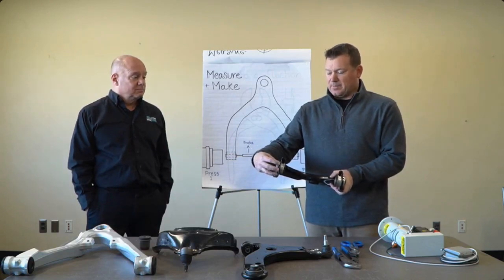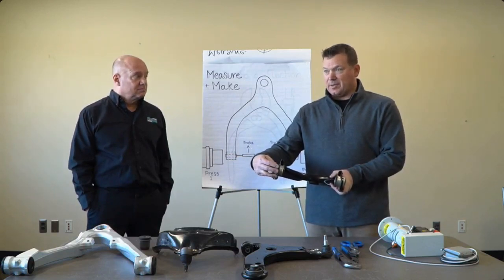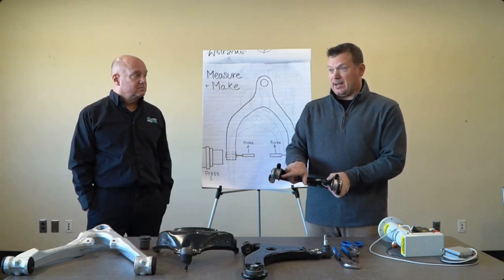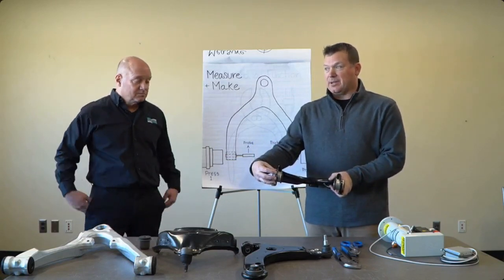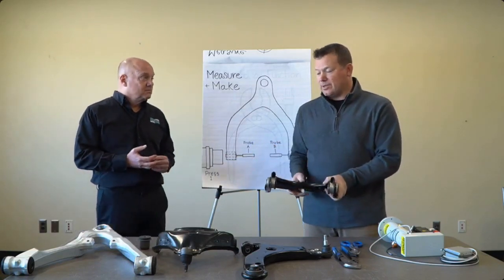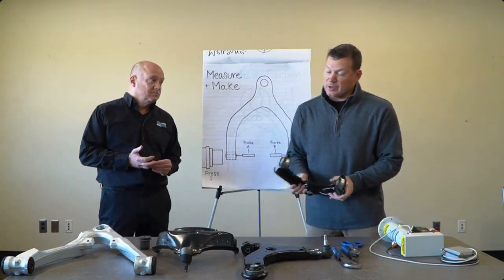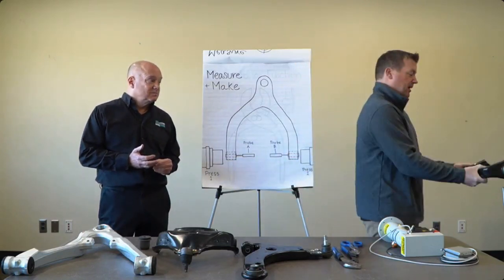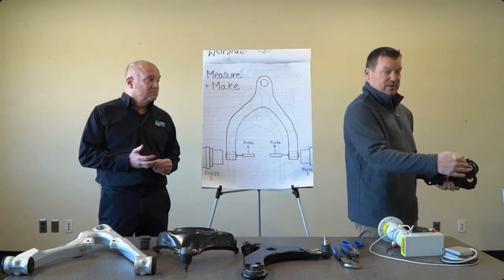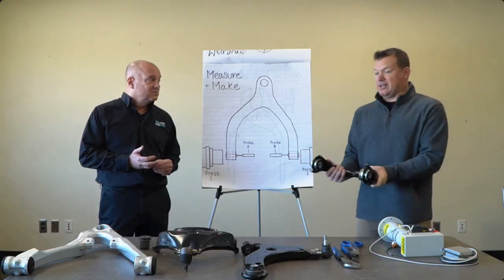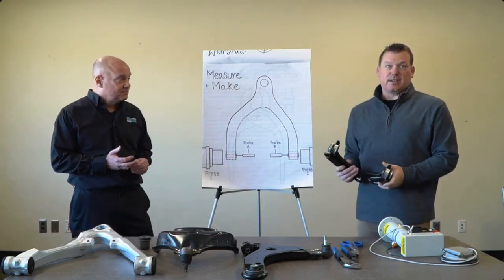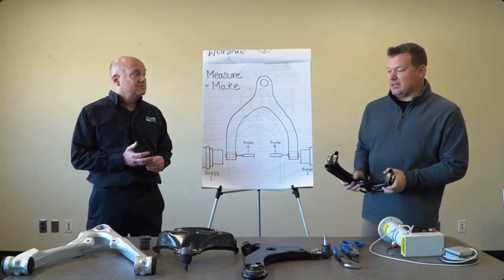So we actually back off, take the force off of it, but the probe still maintains contact, and then we get a real measurement there. So not under load is when we take our measurements. If you do have an offline gauge, it's generally not under load because you're not pressing anything. You're simply gauging it, and it gives you the same reading, and then you can pass capability and gauge R&Rs and things like that.